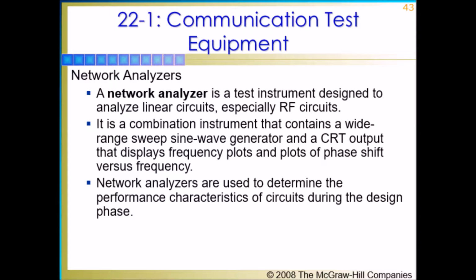What are vector signal analyzers and generators? A vector signal generator is a variation of an arbitrary waveform generator. In some instruments, the signal may be generated at a lower intermediate frequency and then mixed by an up converter to the desired higher output frequency.